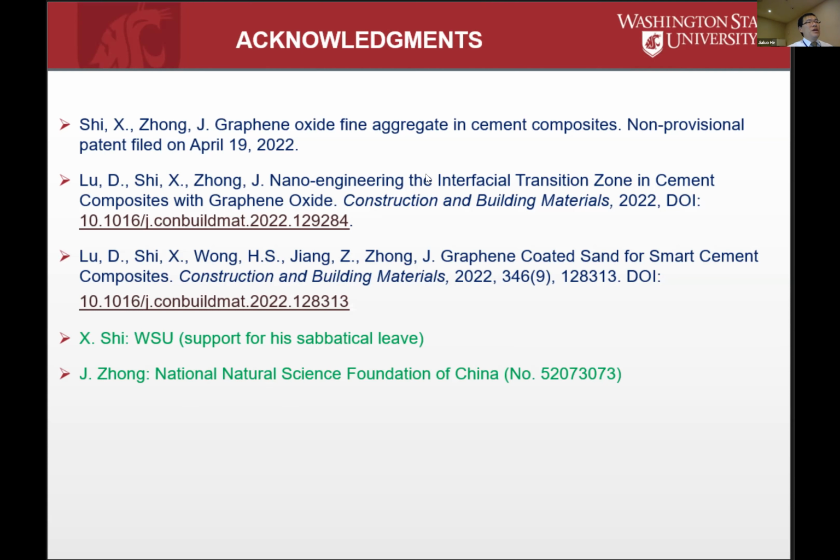Right. Very good question. So why start with fine aggregate? Again, because we believe conceptually the graphene oxide will hold on to the fine aggregate much tighter. And also in many cases, you are dealing with a conductive mortar, you don't necessarily need the coarse aggregate. But yes, like I said, we'll continue into coarse aggregate. And I do believe conceptually it won't hold on to that coarse aggregate as well.